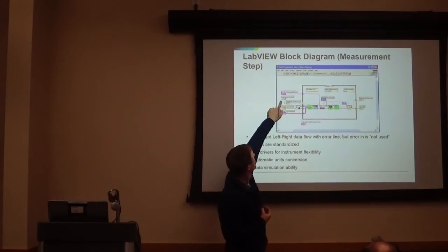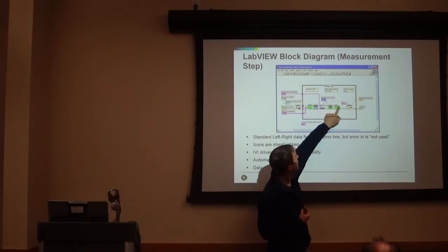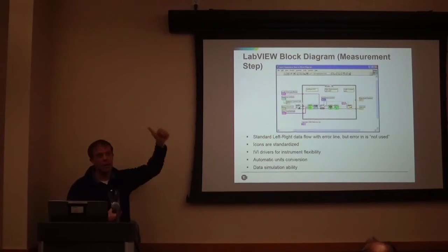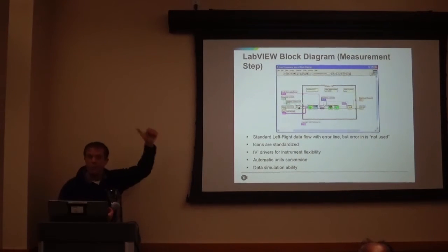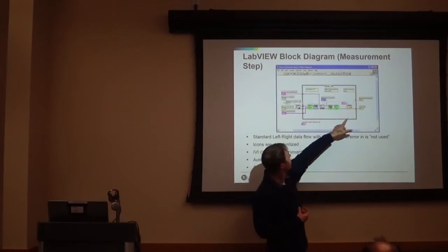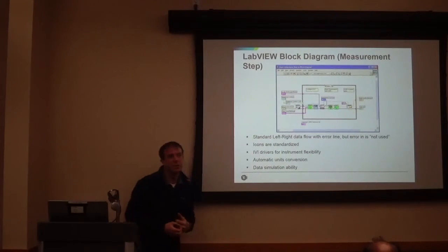And understanding that from the sequence context, I can go back in here and talk to TestStand and say, hey TestStand, I'm giving you this measurement. TestStand knows that the units of this step that I'm executing under are megohms, so I'm going to scale this by 10 to the 6.